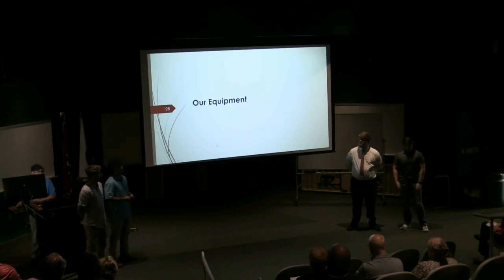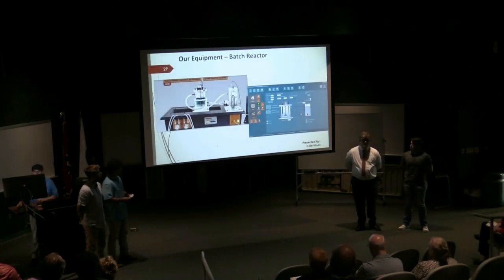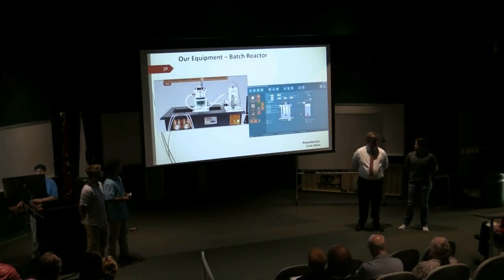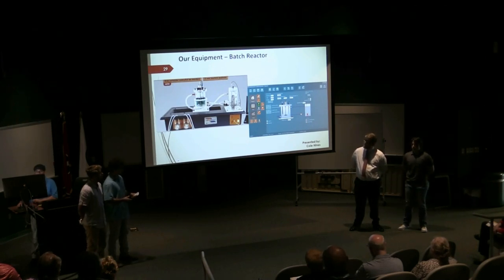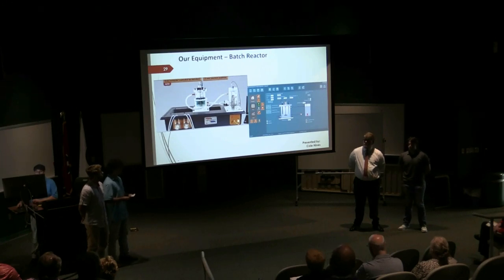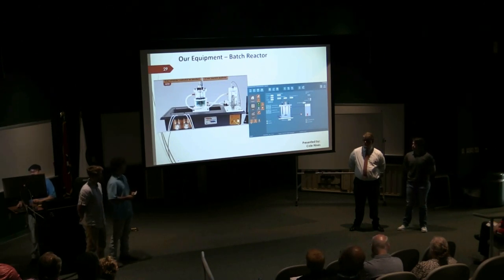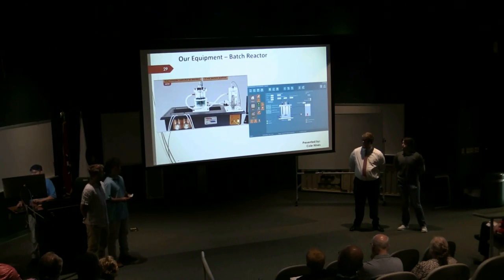This is some of the equipment we use. This is our isothermal batch equipment. It's a star jacketed vessel where we keep a constant temperature bath circulating around it. The program interface on the right there has a built-in data logger which tracks conductivity versus time.